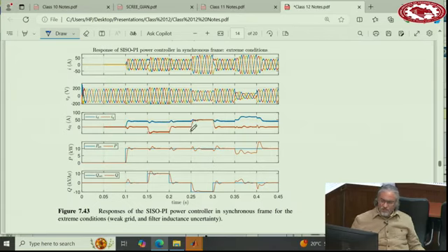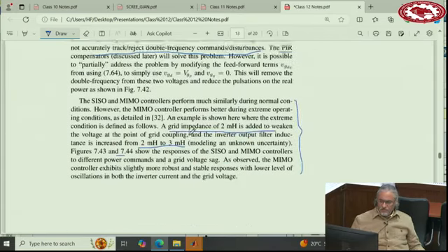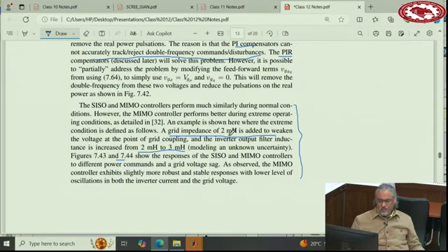And if you keep increasing it, let's say from this 2 millihenry, you go to 2.1, 2.2, 2.3, because you have to go very fine. Especially with the grid impedance, typically grid impedance has significant impact on the stability of the converters, the weak grid situation. I did not cover weak grid conditions in my lectures because that would take at least 2-3 classes itself.